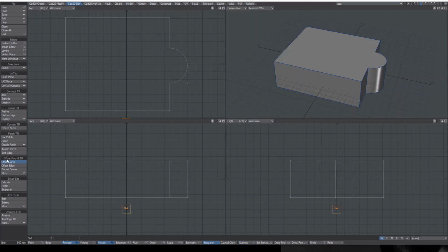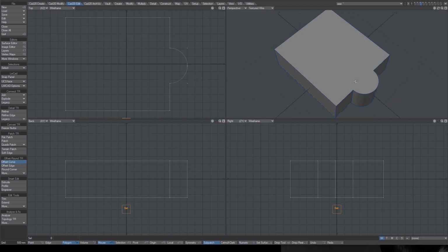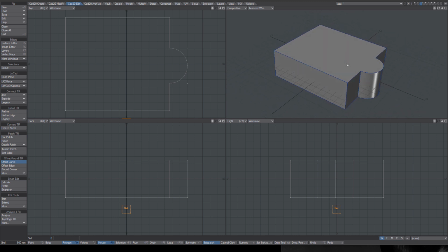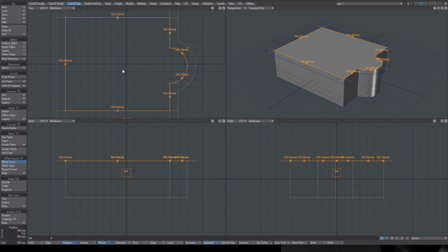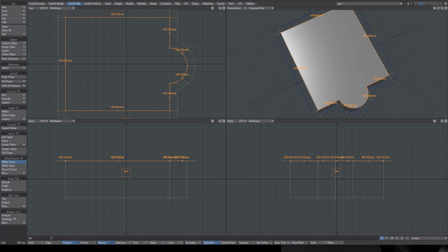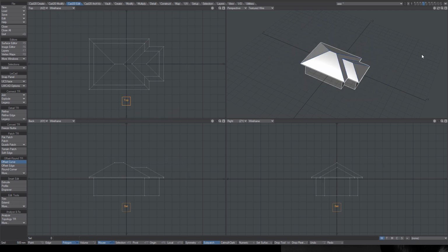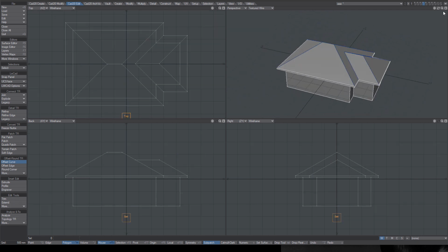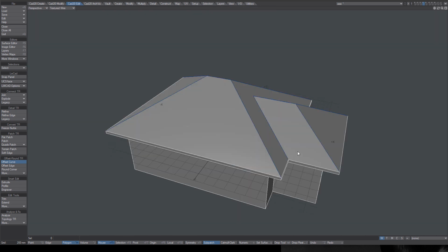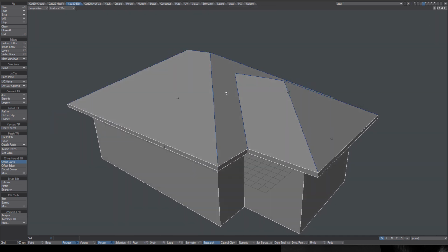Additionally, you can use offset curve tool also on surface object. With Smart Selection, for example, you can select these surface, but offset will be just curves. So you can offset edges of polygons and NURBS surfaces and offset them into curves directly.